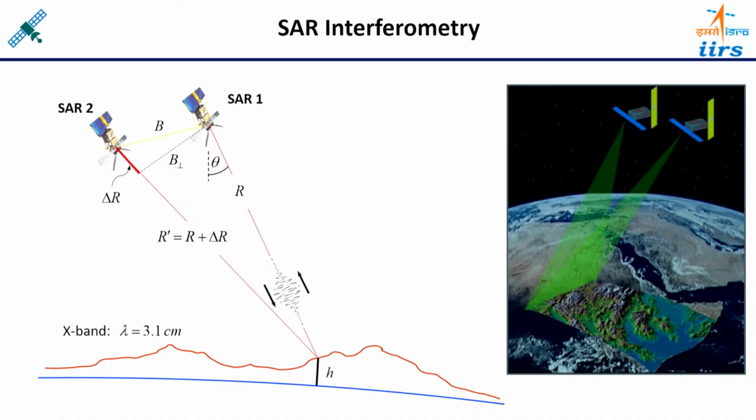So using trigonometry, we can calculate very easily this height parameter. This height parameter is nothing but the topography of the Earth surface. So you can say the topography can be mapped using two SAR images, or by generating an interferogram, or by calculating the phase difference of both the signals, the height can be calculated. Height means the popular application is DEM generation. So SAR based DEM generation is also possible. So this is the SAR application for topographic mapping.